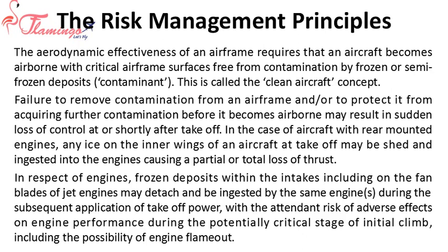In the case of aircraft with rear-mounted engines, any ice on the inner wings of an aircraft at takeoff may be shed and ingested into the engines, causing a partial or total loss of thrust. In respect of engines, frozen deposits within the intakes, including on the fan blades of jet engines, may detach and be ingested by the same engines during the subsequent application of takeoff power, with the attendant risk of adverse effects on engine performance during the potentially critical stage of initial climb, including the possibility of engine flameout.